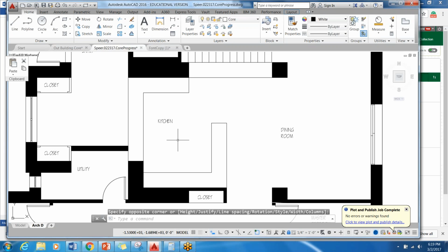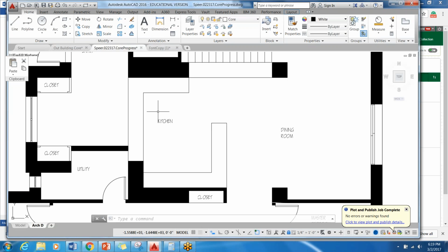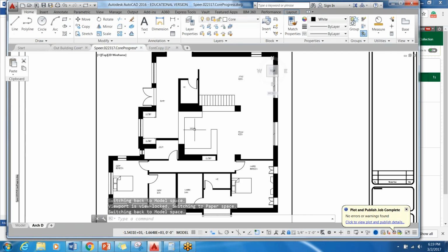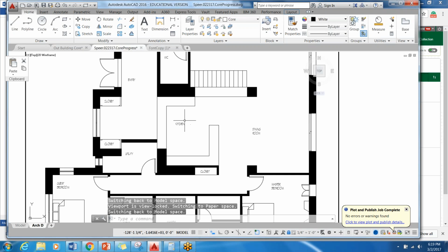Okay, so you're going to have to play a little bit with your scales, although you'll be able to look at mine and see with the Word document like 1/8 equals a little thing, 1/2 equals a bigger thing. But if you think about it, this is a 1/4 of an inch scale of the whole building, and this is only an 1/8 inch size text, so if I wanted something bigger, I would go up the next scale.